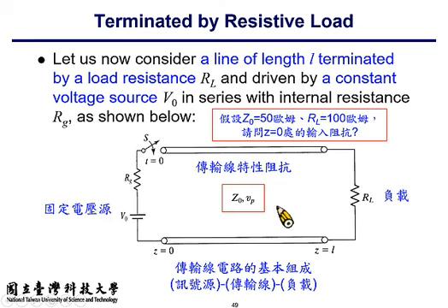Providing that the observation time is long enough, the transmission line effect, that is, the signal bouncing back and forth within the transmission line that I have just described, goes away, will be converged, will be saturated. So eventually, you will only see the resistance of the load. It comes back to circuit theory.